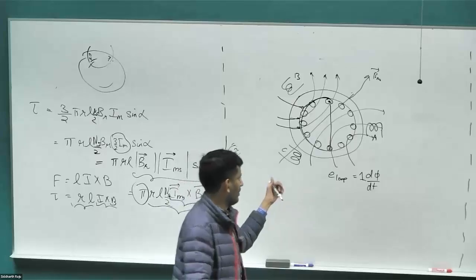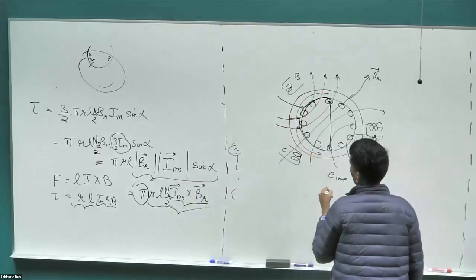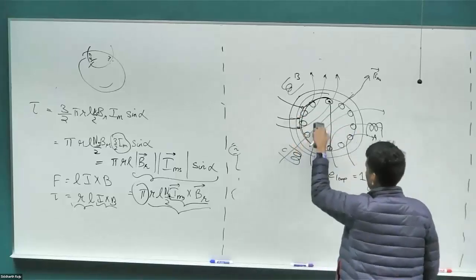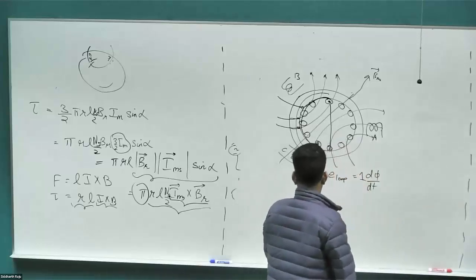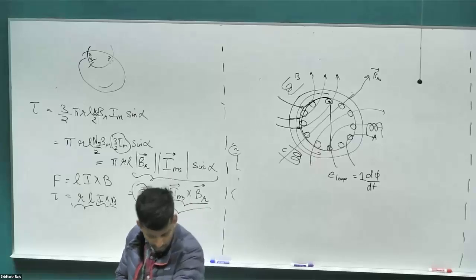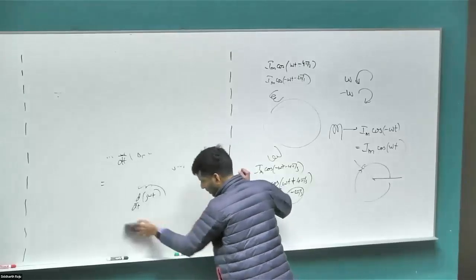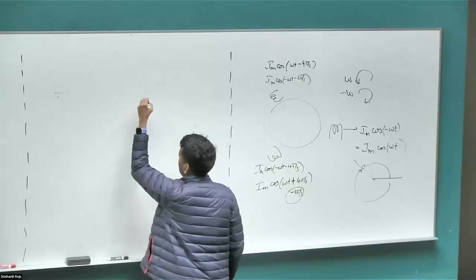That is the same as setting it up as an integral problem. We know what the B field at every single point of this air gap is going to be, right? And we can just integrate the whole thing and figure out what the flux entering is. That will be the same as the flux leaving. And once I have the flux leaving, I can figure out what the differential of the flux is going to be. We already did this when we looked at the case for our permanent magnet synchronous motor. But in any case, let's repeat it.